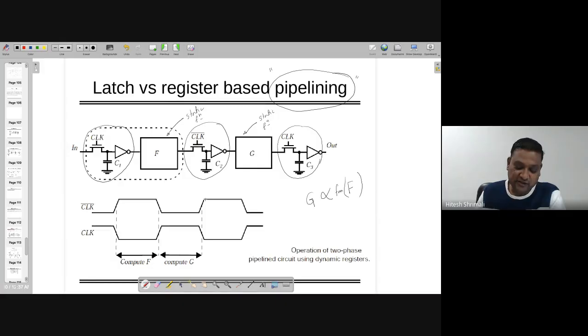I can use dynamic also if I wish, but that might be the advanced one. At the beginning, let's assume that at the clock I want to evaluate this function. If I am implementing it with combinational logic, which was chapter number 6 that we have already studied, using any of those techniques consumes power most of the time, because it's static power. Either side is connected to VDD or ground. In dynamic, you can reduce the power if you want to. But the whole thing is working with the clock.